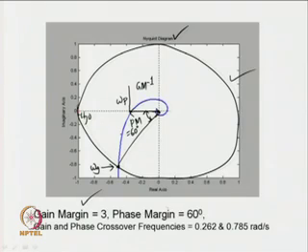So, the better gain margin and phase margin one has, the better stable closed loop system one has. So, stability information, how stable is my controller, how robust is my controller, all those answers can be obtained from the information on phase and gain margins.